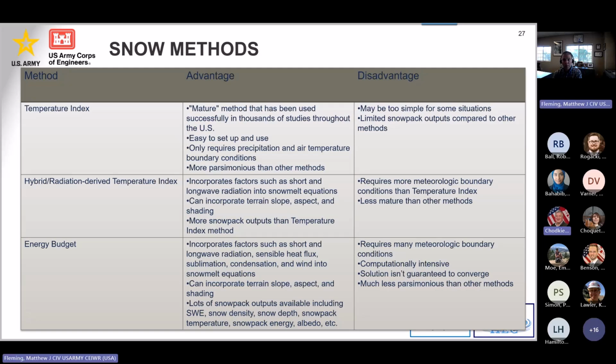It's the wet melt rate, right? That's what's triggered during a rain on snow event, and also your PX temperature. That's the temperature that differentiates between frozen and liquid precipitation, right? So even though there's tons of parameters with temperature index, if you're simulating a rain on snow event, then you just have to worry about those 2.